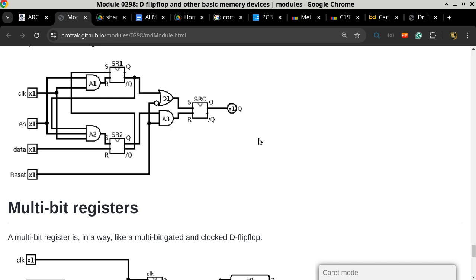Nope. It's going to ramp up from 0 to 5 volts. From our perspective, it looks instantaneous because our scale of time is different from the scale of time of a computer. But from the scale of the computer, it is taking a long time to ramp up to 5 volts. Before it gets to the healthy 5 volts, you probably don't want your computer to start doing stuff, because things are not stable yet.